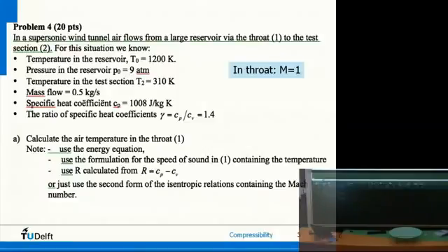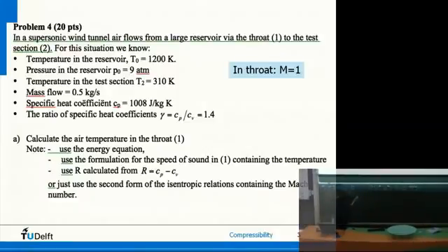Temperature. So we know temperature test. So what does that mean? What can we derive from that? Speed of sound. Perfect. A is square root of gamma RT, so we can derive the speed of sound. So that means this part we know. Now only V test. Any idea how we can find the speed in the test section?